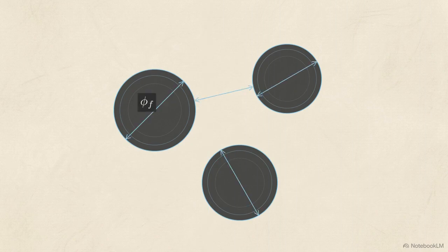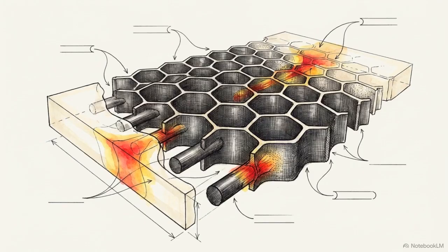Extracting raw data from a physical scan, an algorithm segments the cross-section into a binary mask, isolating every fiber. From this, engineers calculate the foundational fiber volume fraction, measuring the total white area against the black background to determine the fiber-to-matrix ratio. Additional deterministic metrics are extracted simultaneously, establishing the baseline fiber diameter and the average ratio of the gaps between the fibers. However, these basic physical descriptors have a clear limitation.